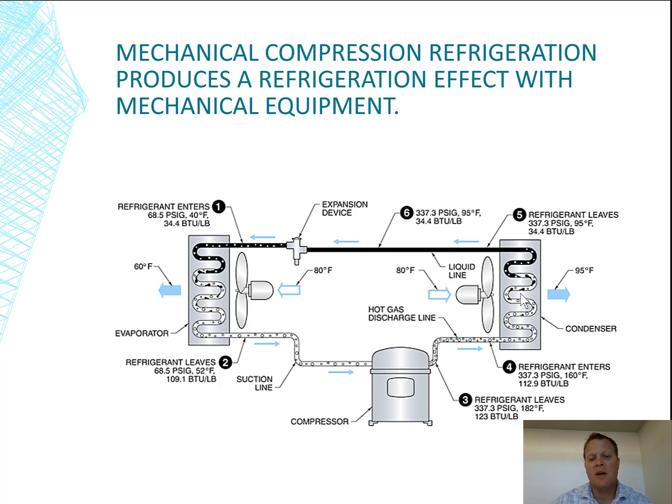And so we've got our condenser cooling off the high pressure gas, turning it into refrigerant liquid. It hits an expansion device. The refrigerant hits this expansion device, which changes the pressure back to low pressure. The refrigerant begins to go under low pressure, so it's going to start to boil.